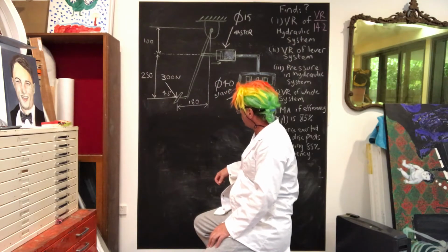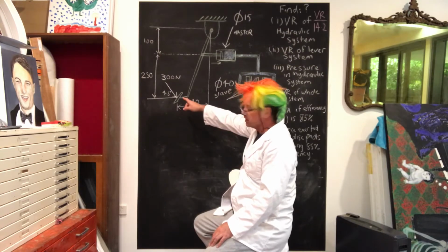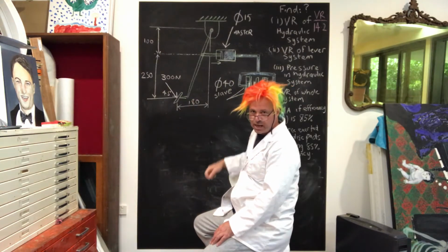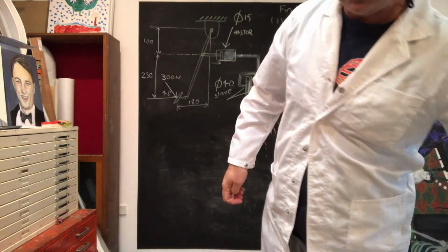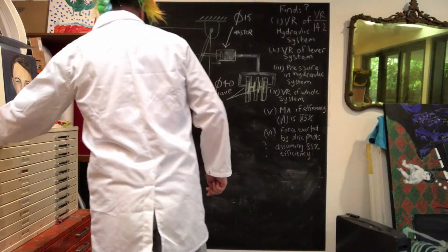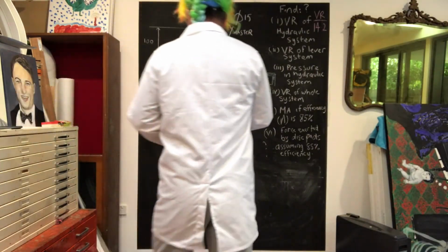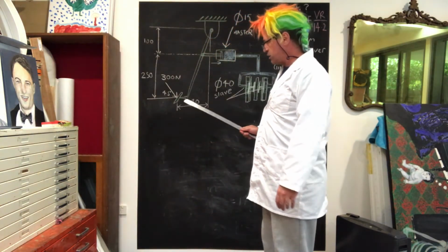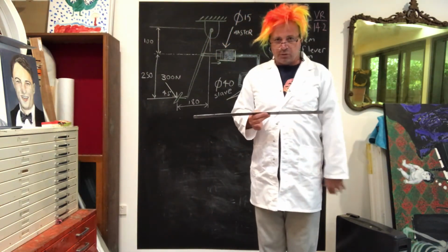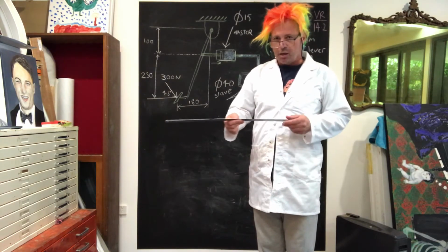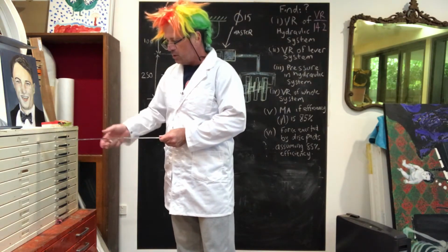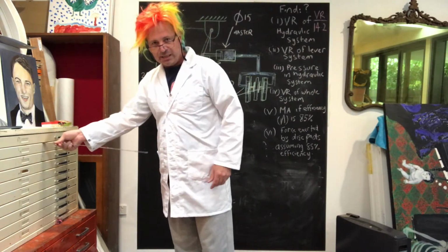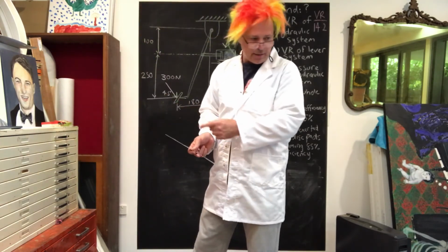Okay, so because we aren't given a perpendicular distance, we can still calculate one. So we're going to try and work out a perpendicular distance. And we need to use another idea that we all should know, and that is transmissibility of forces. We said that if I'm applying a force in this direction, as long as it's applied along the same line of force, I can apply it here, or here, or here. It doesn't really matter as long as it's in the same line, okay?